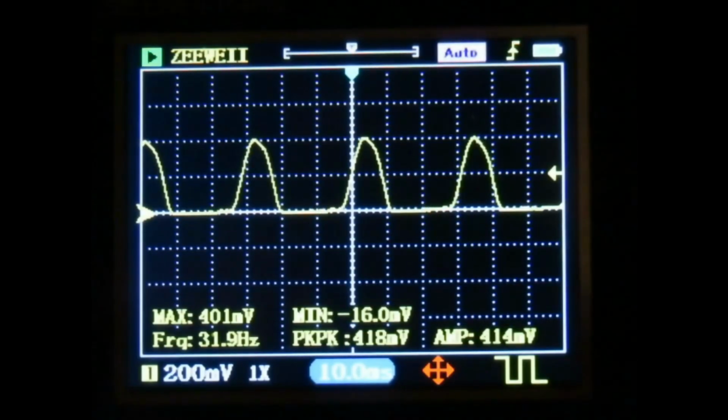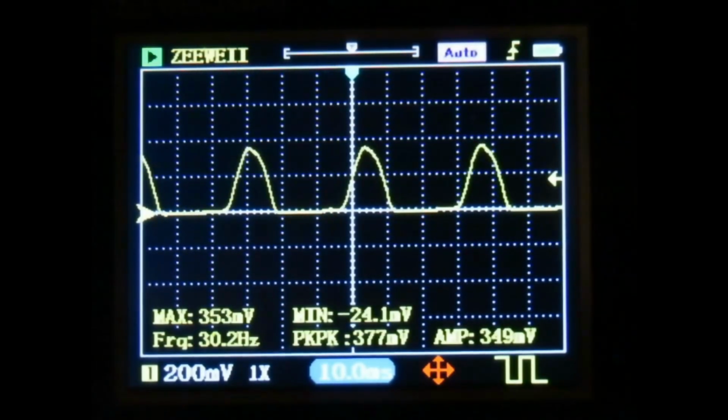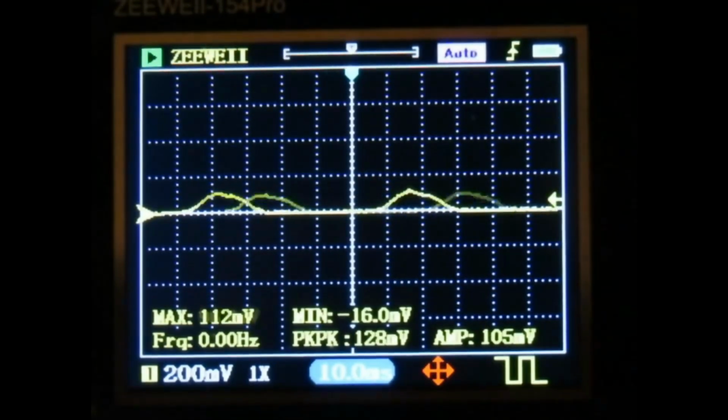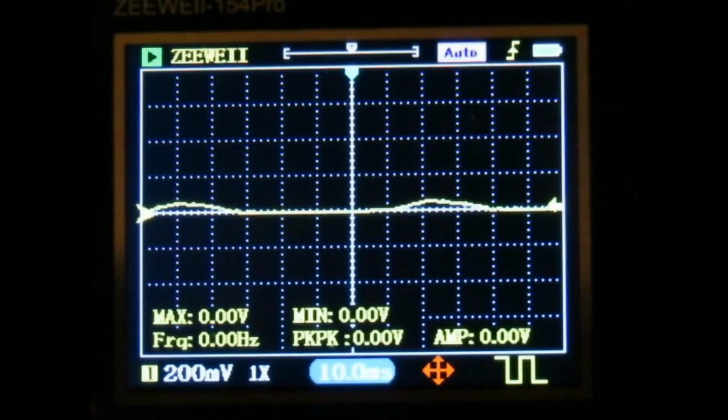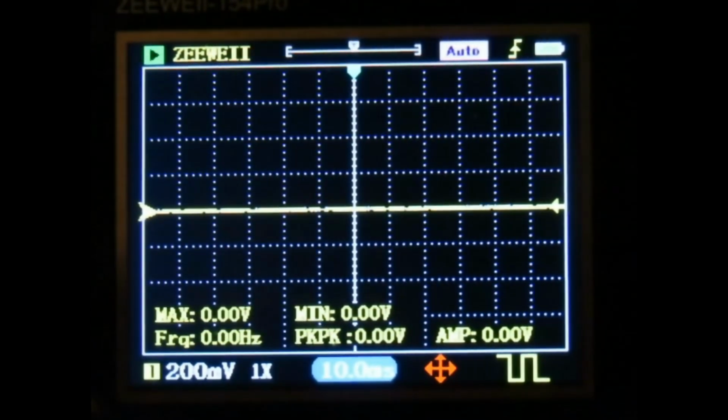If you add two diodes, you can put the bottom of the cycle up on the top of the line, and you'll have full wave DC. The other one was called half wave DC, or half wave rectification. It's all flowing in one direction, but in pulses.